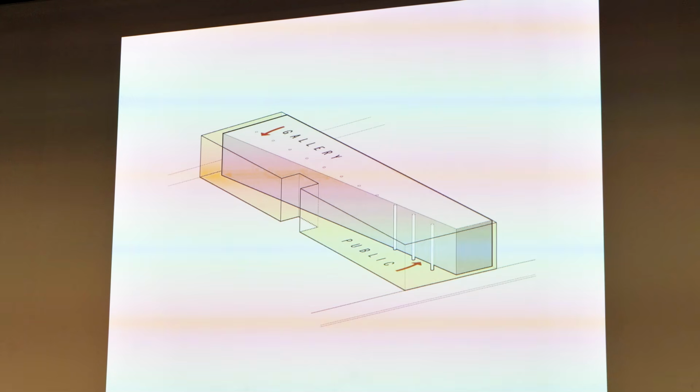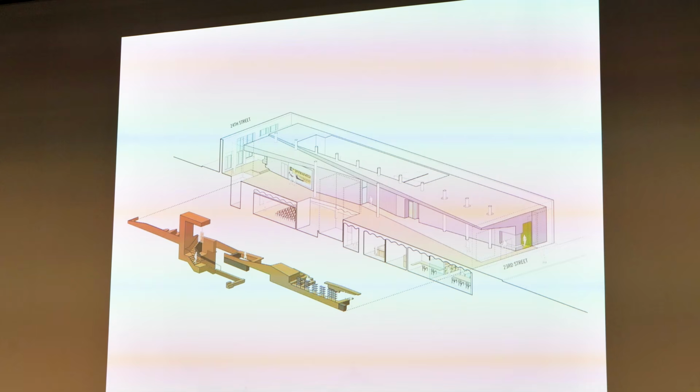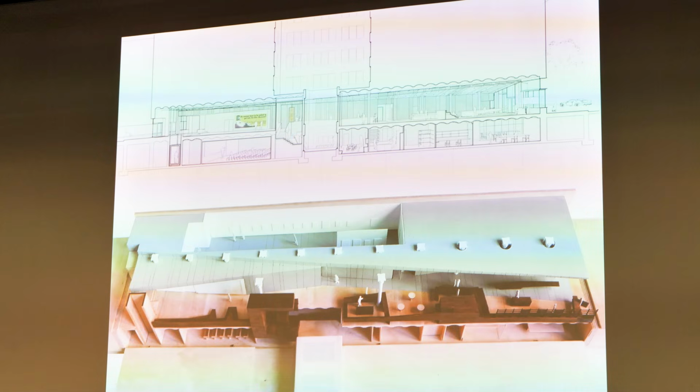Tweak this so that you can get the right weights of where you want spaces, and then carry out a canopy so that it really reinforces the idea that you're walking within a street, even though you're inside. Provide a secondary entrance on the back side, then insert an armature of bamboo and wood on one side that would be all the amenities, services, gift shop, etc., and then provide the gallery on the other side and more support spaces on the lower floor with a connection through the wood and bamboo.